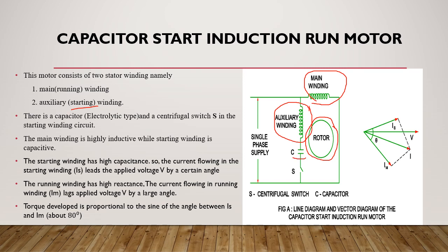There is one capacitor here. It is connected in series with the starting winding. That is why its name is capacitor start. And then the centrifugal switch is also connected in series with the starting winding. The main winding is highly reactive, and the starting winding is capacitive because there is one capacitor there.